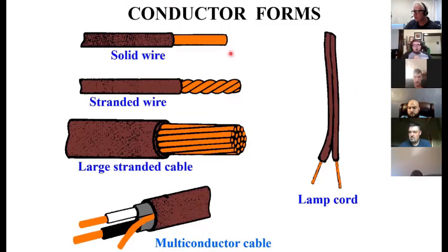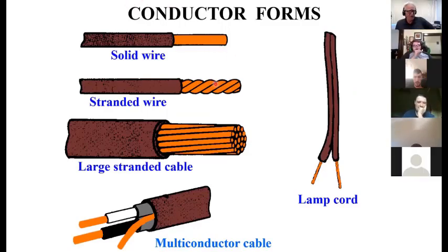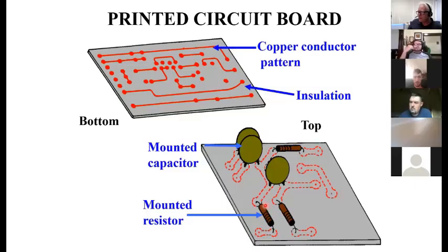Solid wire and stranded wire. Imagine your extension cords if they were stiff wire and you had to roll them up every time and unroll them. They're just not made for that, and they will break over time. So solid wire, a good application for that is where you're going to put wire up and you want it to stay there, like when you're wiring your house and you bend it and it kind of just stays there on its own. You might have to put a staple here and there. But stranded wire is really good and flexible. It's a matter of flexibility. Printed circuit boards, you've seen the traces on a board, they're conductors.